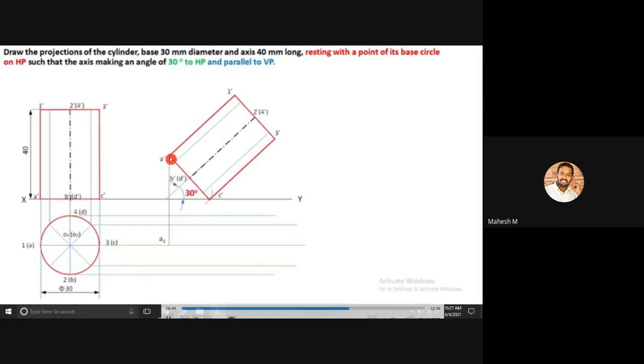Then you can project your bottom surface towards the top view position. We have already created a horizontal line from our previous top view. Okay, so you'll be having 8 points in the base, and also you'll be having 8 points in the top surface. So if you're looking from your top view, you can see your top surface fully and the bottom surface is not fully visible. That means you can create half of the ellipse with a dark line, and the remaining half should be marked with a dotted line.